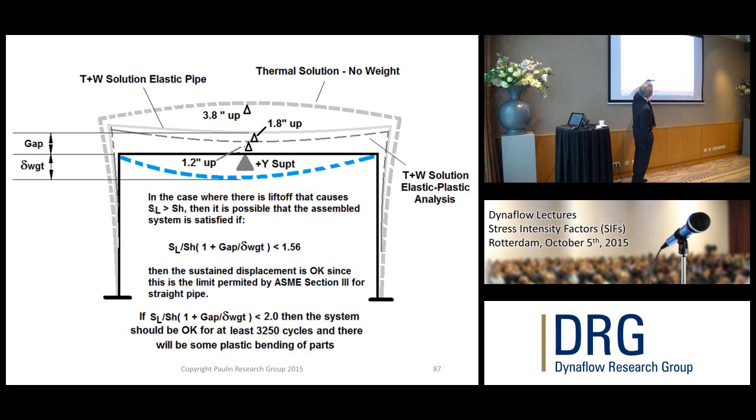What it basically says is that when you have liftoff, you can go through this evaluation for each location and decide if it should be overstressed or not. What's that based on? It's based on twice elastic slope. Twice elastic slope is based on the concept that you've collapsed when your elastic analysis predicts 1 inch and you really get 2 inches. You get double what you calculate.